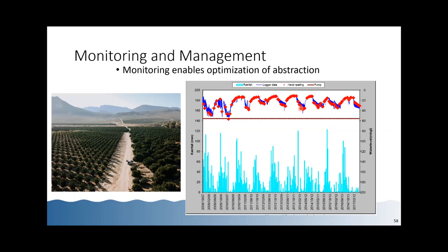You will notice that when we started with monitoring, the water levels were initially drawn down to pump inlet. There were issues with pumps burning out. And apart from those first 2 years, you can see how the abstraction is sustainable. And this is really just a great example of informed management of the supply source.